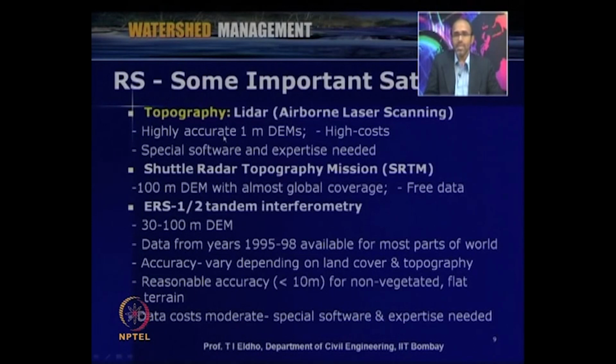And then, depending upon the purpose, whether we are looking at topography, climate related parameters, or vegetation, accordingly specific satellites are available. So, if you are looking for topography, then there is LIDAR, which is airborne laser scanning based.